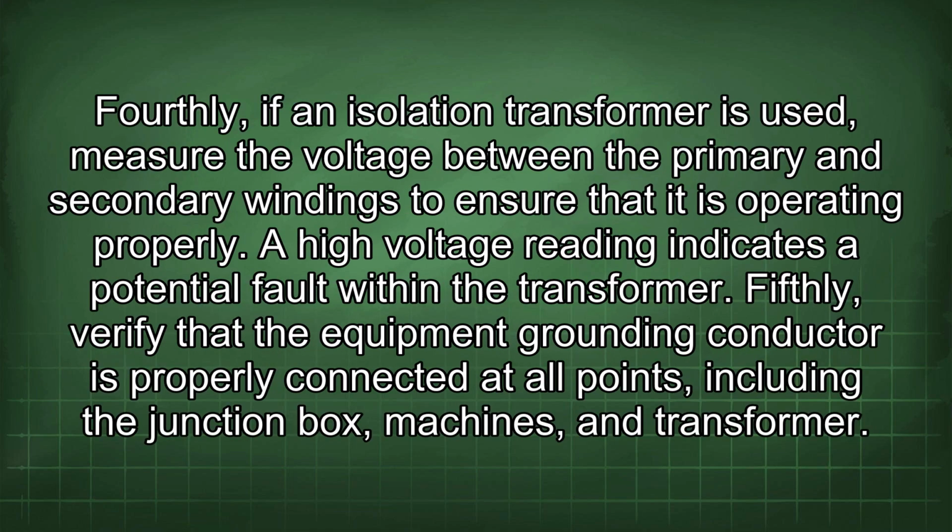Fourthly, if an isolation transformer is used, measure the voltage between the primary and secondary windings to ensure that it is operating properly. A high voltage reading indicates a potential fault within the transformer.